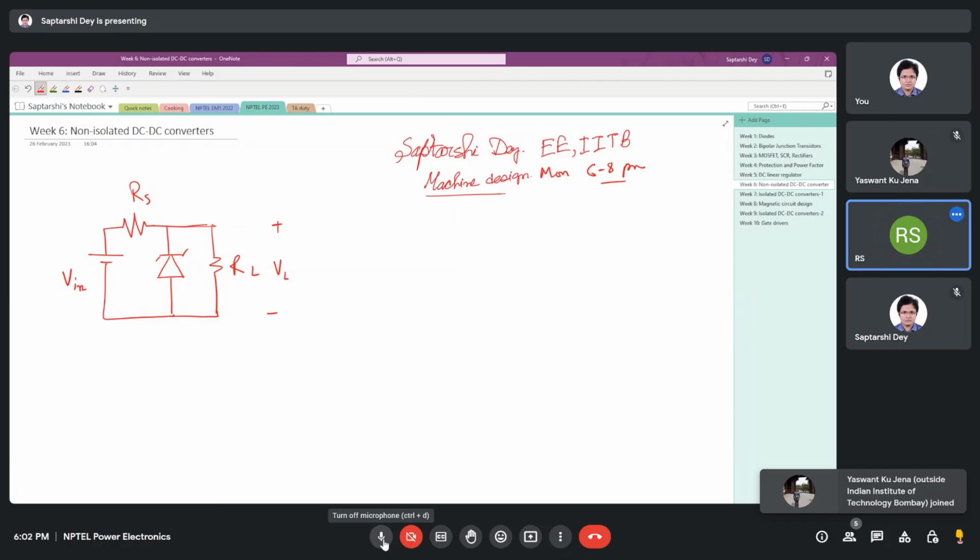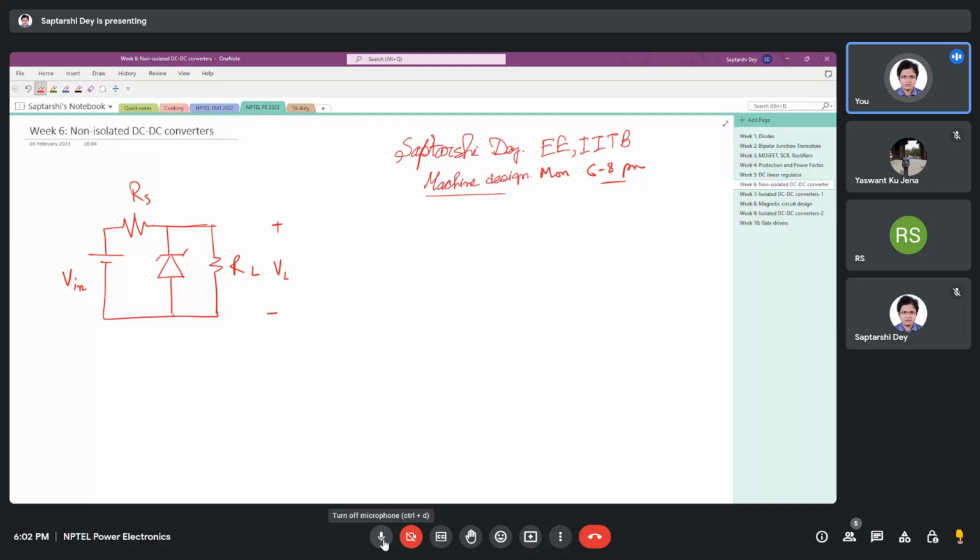So you do not calculate RL, right? Or are you talking about some maximum or minimum value of RL? That maximum RL that we can connect here, sir. In that, for I min current flowing from the source, we are calculating the RL by removing zener.